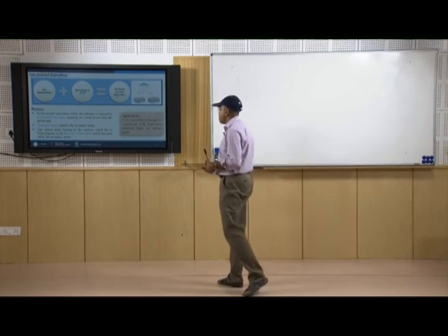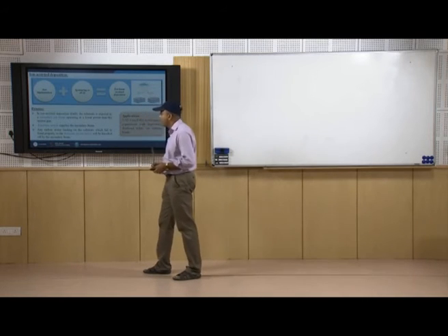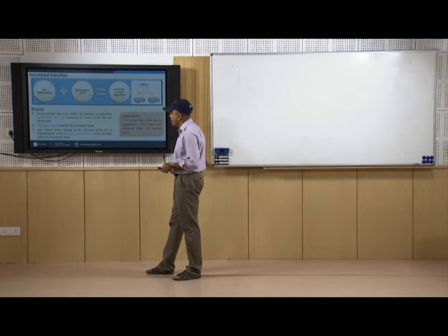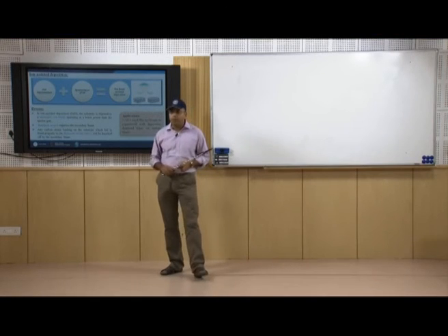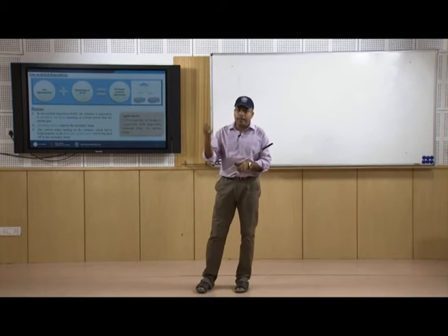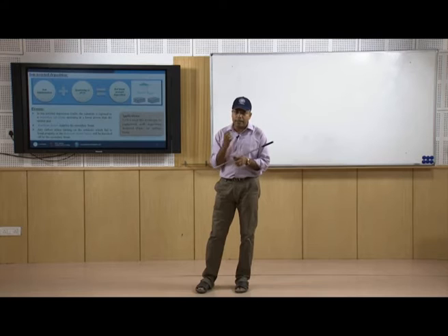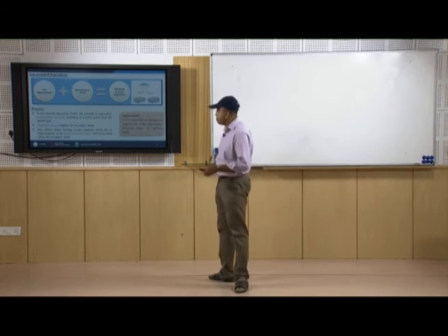The substrate is exposed to a secondary ion beam operating at a lower power than the sputter gun. A Kaufman source supplies the secondary beam. Any carbon atoms landing on the substrate which fail to bond properly in the diamond crystal lattice will be knocked off by the secondary beam. So simply, the powder is coming and hitting your substrate, then you apply the secondary ion beam, which gives a temperature so that any unbonded nanoparticles can stick properly onto the substrate itself.